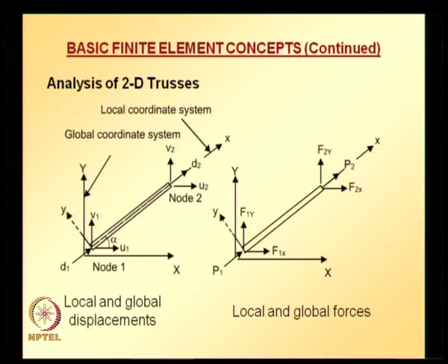And in today's lecture we are going to look at how to analyze truss members, analysis of 2D and 3D trusses. Before we look at the derivation details, let us see what truss members are. Trusses are structural frameworks in which individual members are designed to resist axial forces only. They are commonly found in roof structures and bridges. The equations for these elements are well known in the structural engineering field and usually are covered in traditional courses on matrix structural analysis. Element equations can be derived from the axial deformation element using simple coordinate transformation.